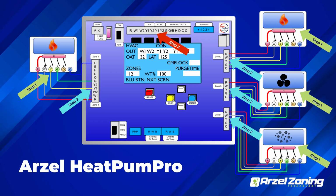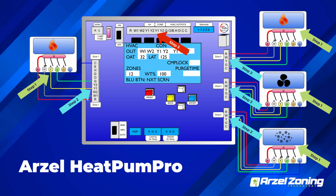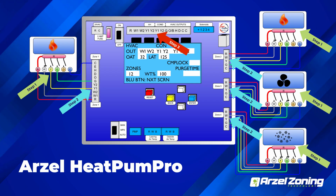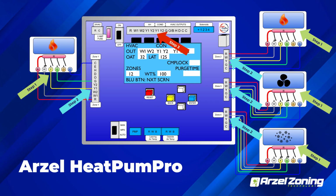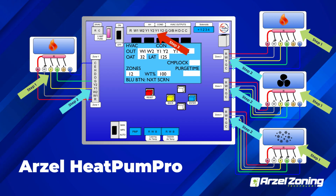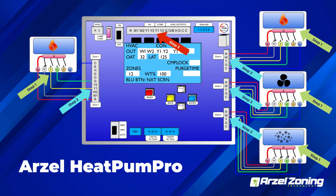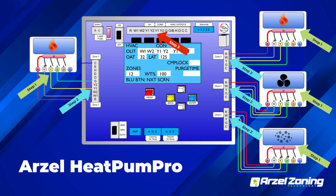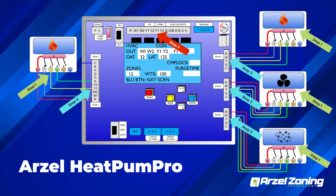So with the HeatPumPro, we can view our thermostats individually, and we can focus on that specific thermostat, that specific set of zone connections, because that's our thermostat and our equipment, and we can see where our problem's at on that specific zone. So it might be broken thermostat wire, it might be a bad thermostat. Rather than trying to diagnose all 4 zones in our equipment at the exact same time, we break it down into individual zones. Each zone has a thermostat.